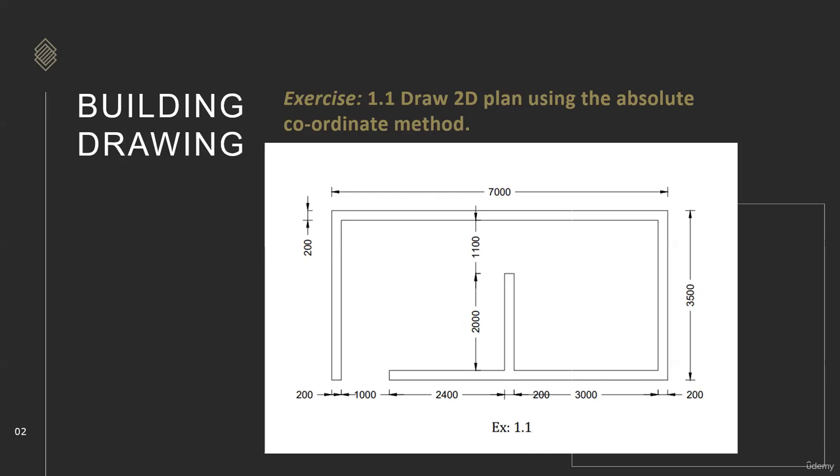That is the dimension of the rooms, the overall outer-to-outer dimension. So if we give the paper size as 4200 by 2970, then obviously the plan will come out of the particular limits, correct? So here we are going to change that. Whatever dimensions are given, we'll change that. We are not using the A3 size paper here.